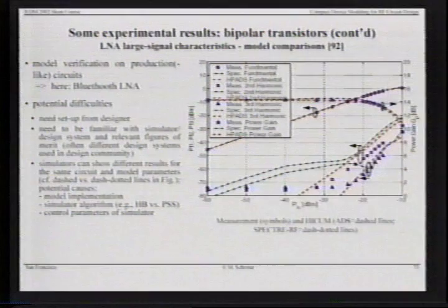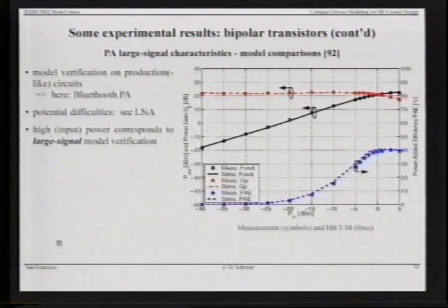And the interesting thing is that the simulators, these are two different well-known simulators, differ at low power levels significantly, as you can see here. This is something I would really like to point out, that designers have to be aware of the fact that the simulators can give you problems when you compare. It's not always the model. Don't always blame the model and say, oh, the models are bad. Just look sometimes at your simulator, and you will find that also the simulators don't give you the right results or the same results. That is actually a serious issue still for some of these high-frequency simulators and simulations.